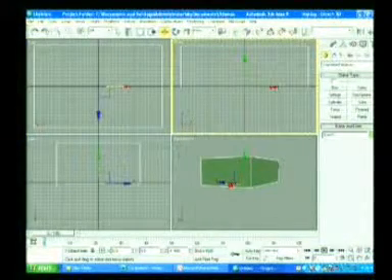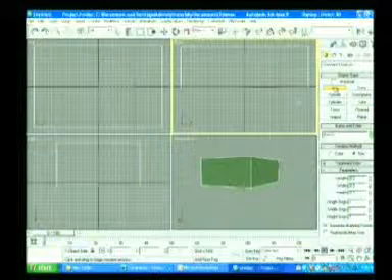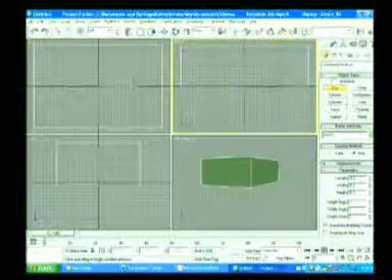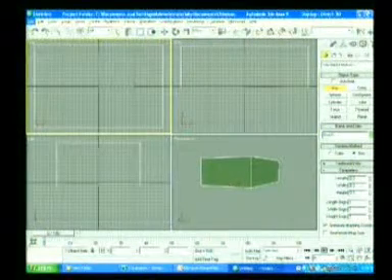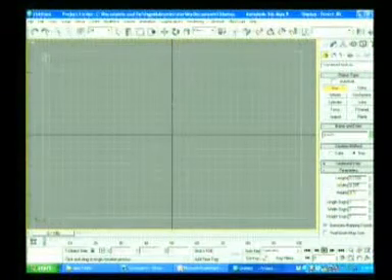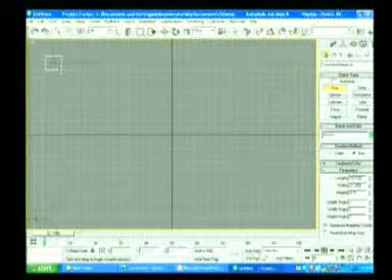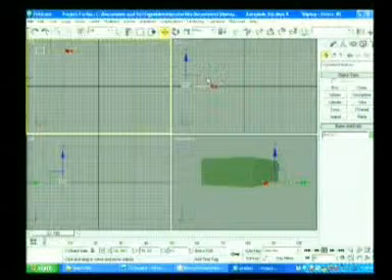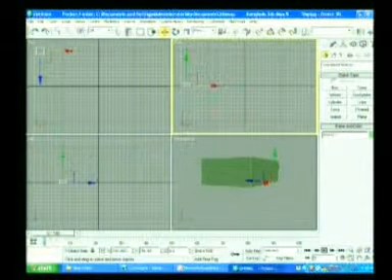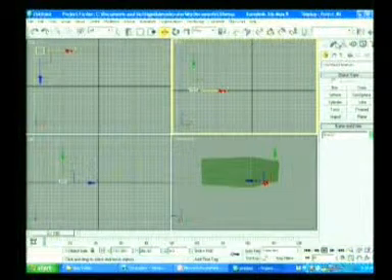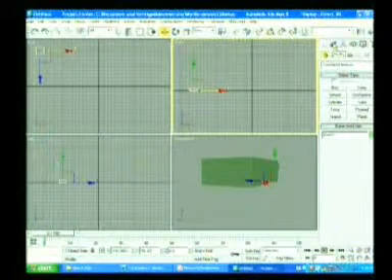This comes in basic modeling, like we have another box. Select the top view. Whichever view is selected, it's going to have a yellow border. Select the top view and make another object. In front view we can see the height of the object, and here we have a modify panel.